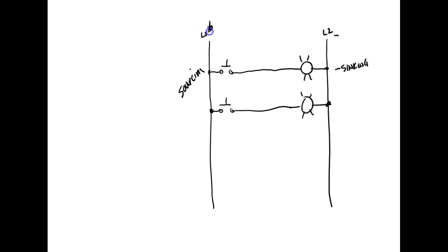But I could just as easily make this negative and this positive. Now this is no longer sourcing. This is syncing. Now when we get to PLCs, the input modules, the inputs and the outputs, have to be powered up.